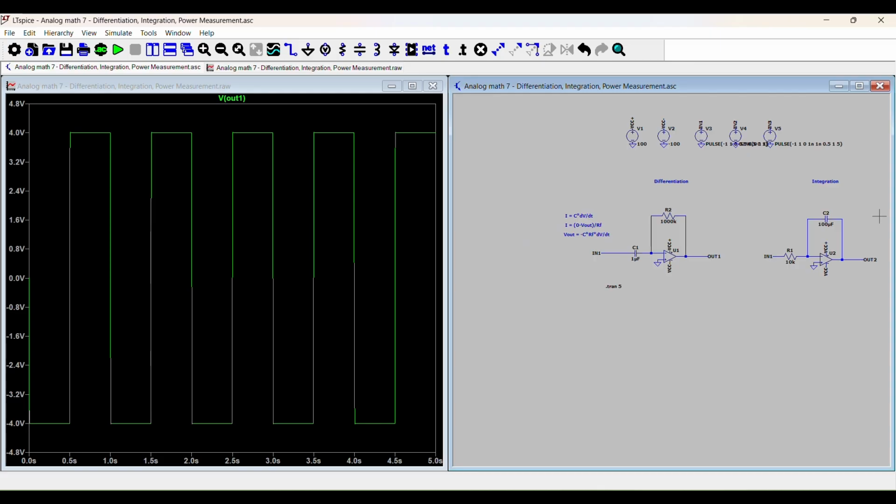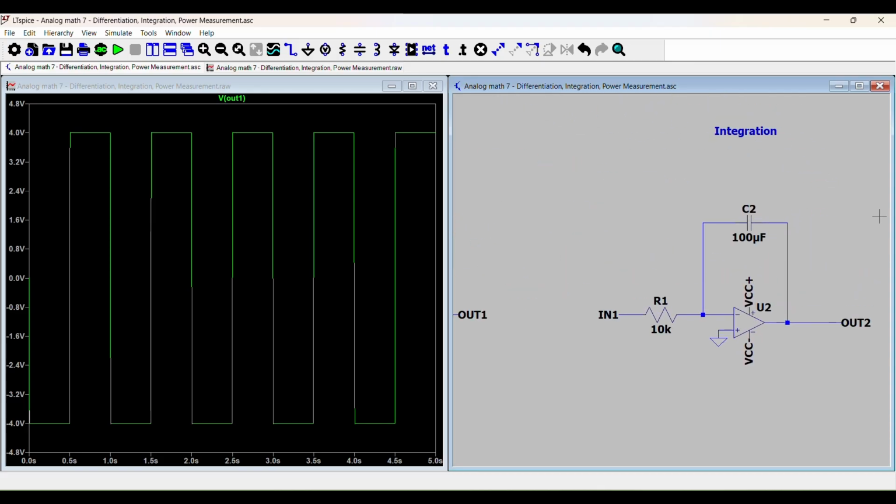So next, let's look at how integration works. If you haven't seen my op-amp feedback tutorial, basically how to invert any function by putting it in the feedback path of an op-amp, I suggest you watch that first. But essentially, by putting the capacitor in the feedback path of an inverting amplifier configuration, we are inverting the current to voltage relationship through the op-amp.